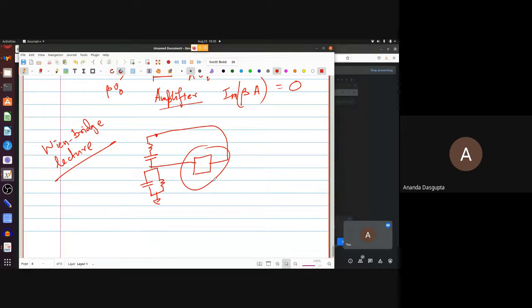In this oscillator, basically what happens, I'm just going to give you the answer in a way, without giving you the details. The gain of this amplifier is given by something like this, 1 plus R2 by R1, where R2 and R1 are two resistances. You need to know only this much for the time being. Why is this 1 plus R2 by R1? We are going to talk about that in some detail later. R2 and R1 are just two resistances. That's all you really need to know.